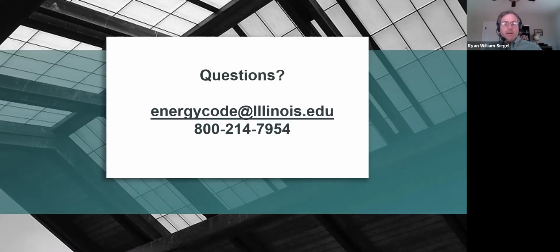All right. Have a question here, and someone's calling out that one of the other methods for compliance with the International Energy Conservation Code is through using the ASHRAE 90.1 standard, which is generally whichever one is previous to the International Energy Conservation Code.